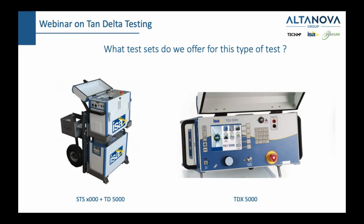Can tan delta depend on measurement frequency? Yes, it does depend on measurement frequency, but not so much. Let me just say that we will talk next time about frequency sweep. This is when we do tan delta at different frequency levels. It depends on the frequency, but not very much. If it starts to depend very much on the frequency, then we have a problem with the insulation.